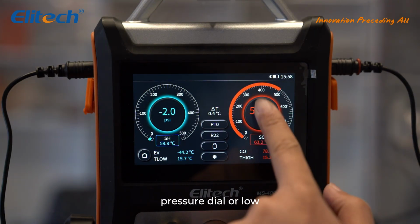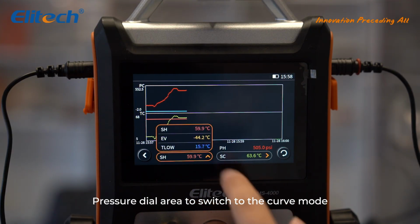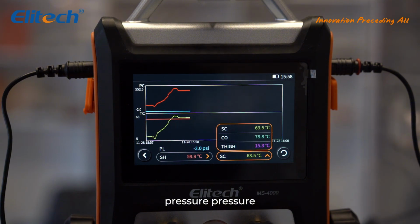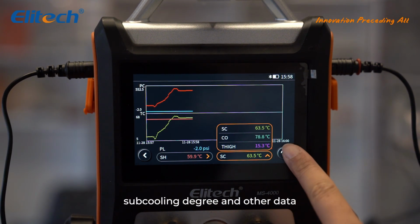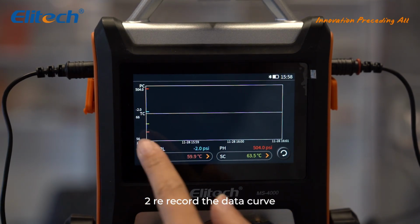Click the high pressure dial or low pressure dial area to switch to the curve mode. The curve interface can view the curve changes of low pressure, high pressure, superheat degree, subcooling degree, and other data. Click the restart button to record the data curve.